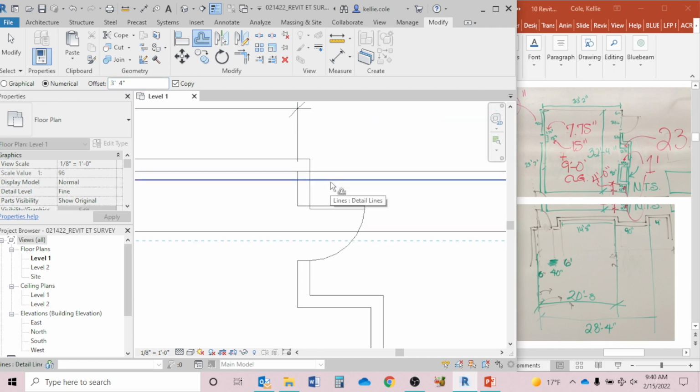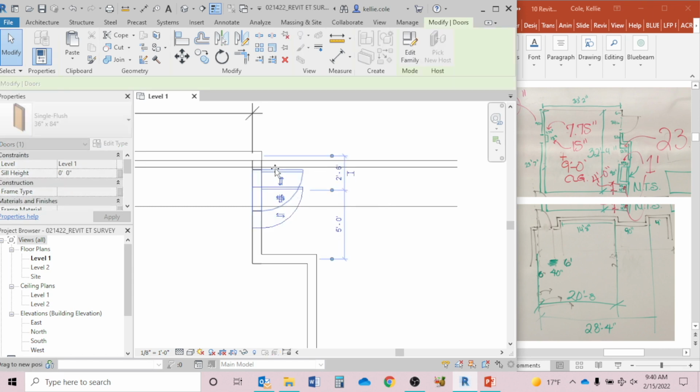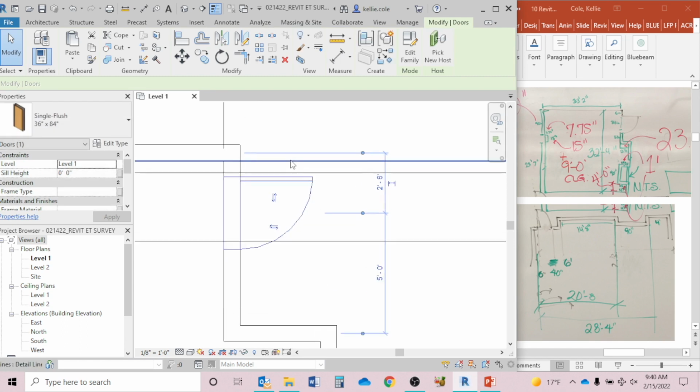It can be a little difficult because you accidentally might grab another line when you use offset. So another option is copy. Let's move the door. So I see that that's the first edge of the wall, 0 point, 6 inches for jamb. Grab your door, hold down the cursor, and move it up. You can do this imprecisely by using arrow keys as well. So I'm just touching my up arrow to center that door in that 3-foot dimension. Revit doesn't have jambs on this door, so it's not going to be exactly aligned. That's okay.